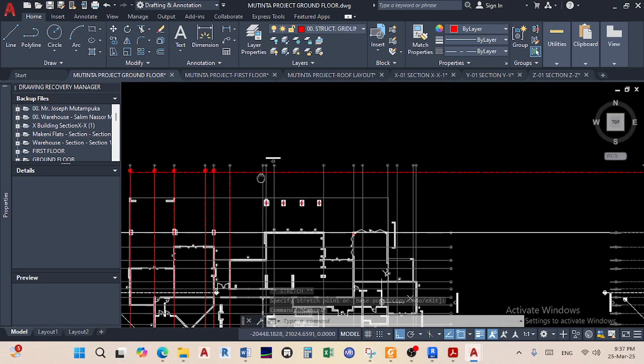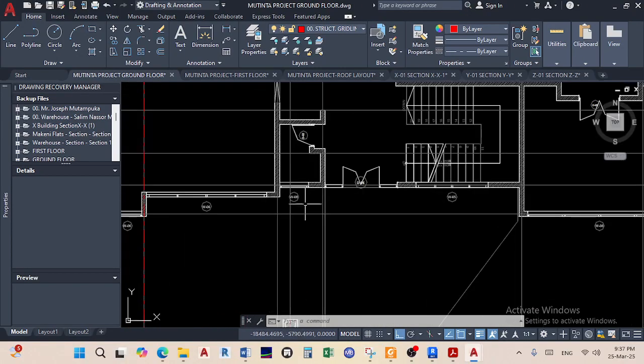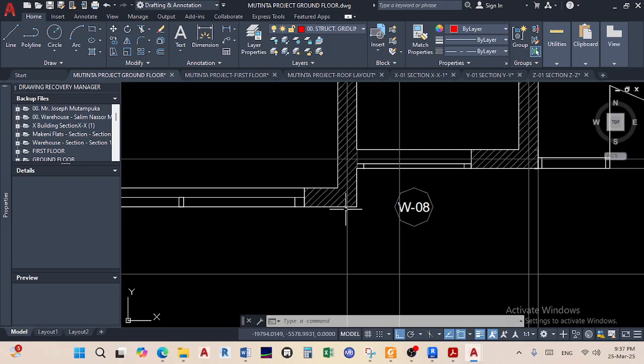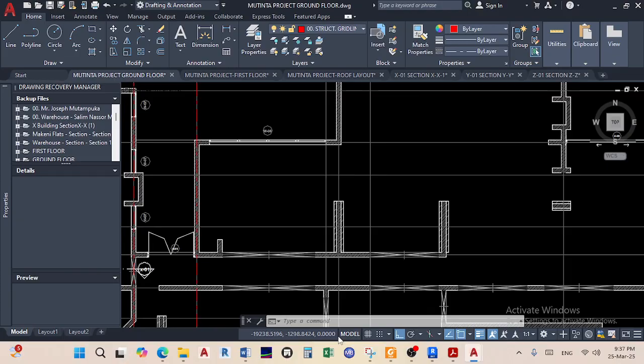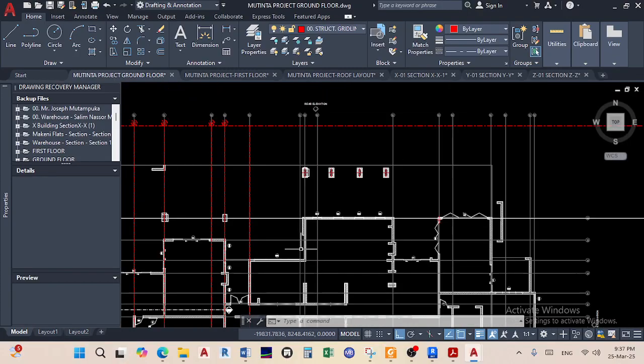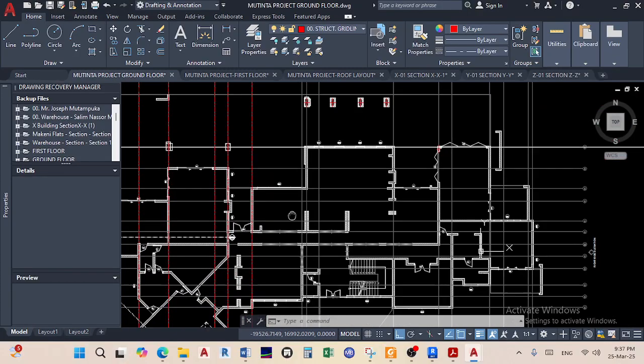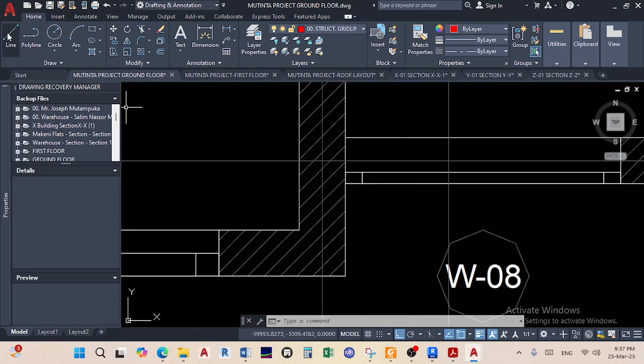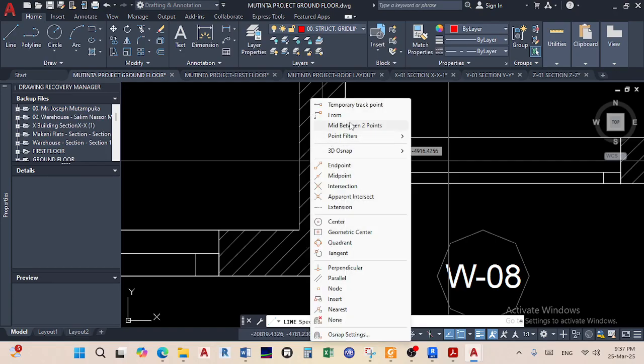And then I'll go to my 7. If I really wanted to be quick, I could copy all of these and just paste them right in these existing center lines. But the only problem is that I'm not sure whether those center lines are accurate or not. So you could either follow the architect's center lines, or you can confirm them yourself.